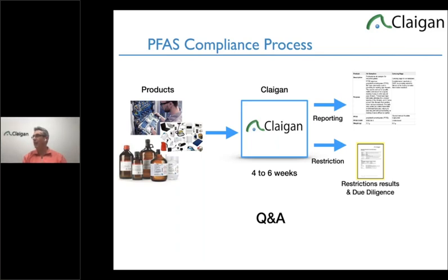What typical industries use solid polymer parts? Not Teflon coated PFAS. Medical for sure. Laboratory equipment all over the place. If we take a typical piece of laboratory equipment, it's full of fluoropolymers. Anything that really transfers chemical fluids, we'll use Kynar, which is PVDF.